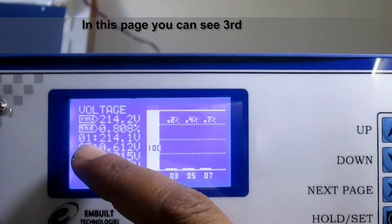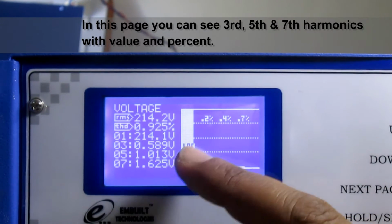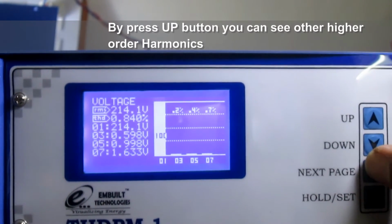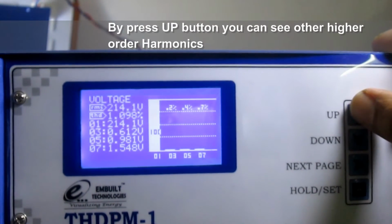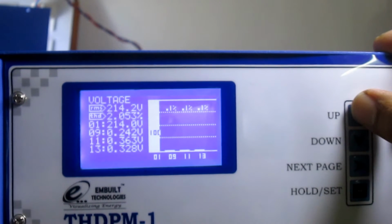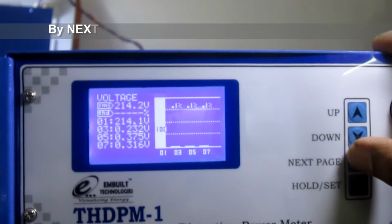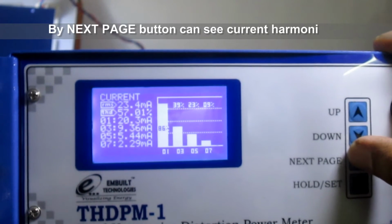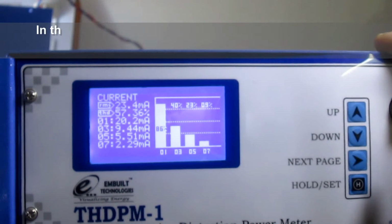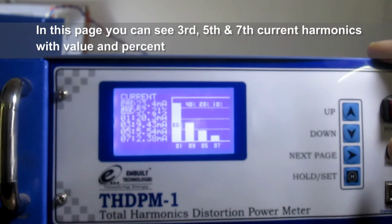Harmonics. Presently we are seeing the 3rd, 5th and 7th harmonic, and pressing the up button we can go up to the 55th harmonic for voltage. On the next page, if we press the next page button, we can see the current harmonics. Similarly, it shows the value of the harmonics as well as a graph.